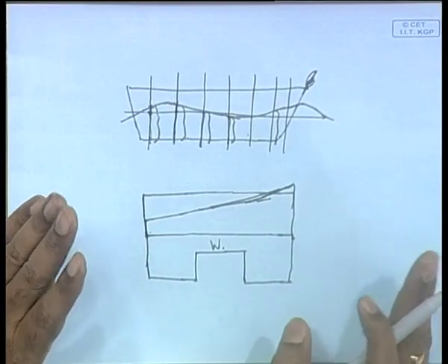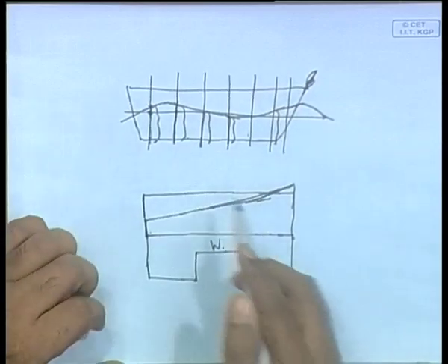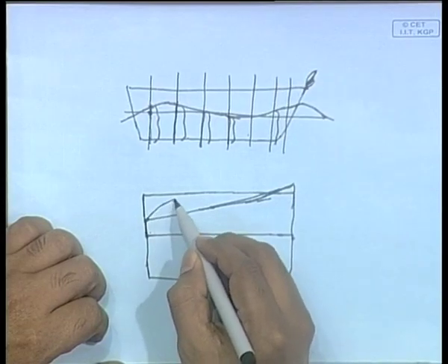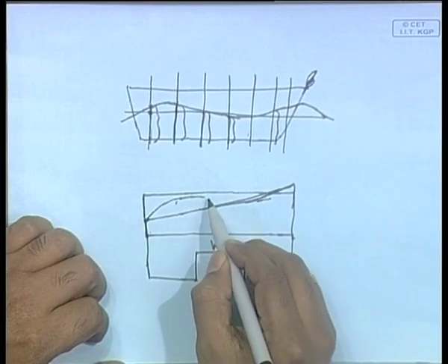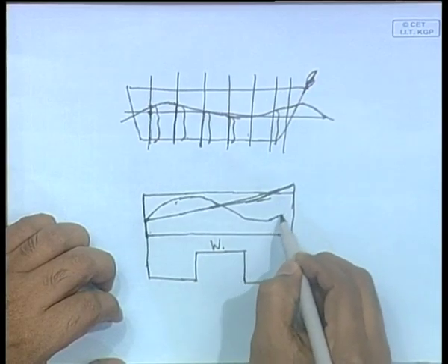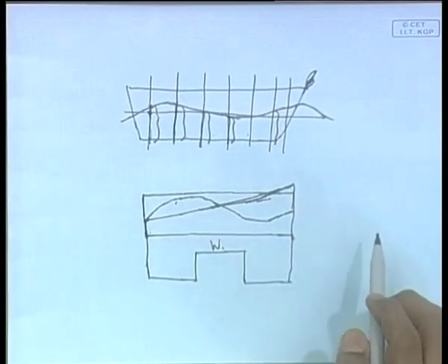But in the case of a ship that is now on a wave, its buoyancy will be completely according to that wave. So, maybe like this, of course, we are assuming it is a box shaped barge. Depending upon where the ship is placed on that wave, the water line will vary, where is the crest, where is the trough, and as a result you have the buoyancy curve varying with distance along the length of the ship.